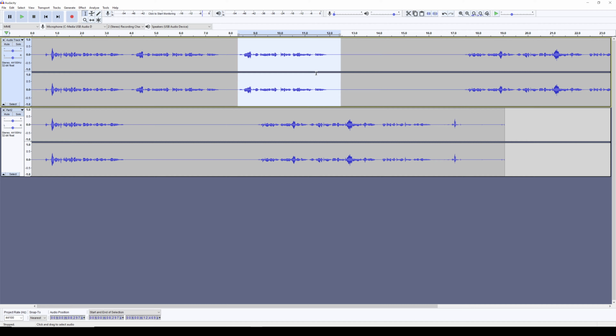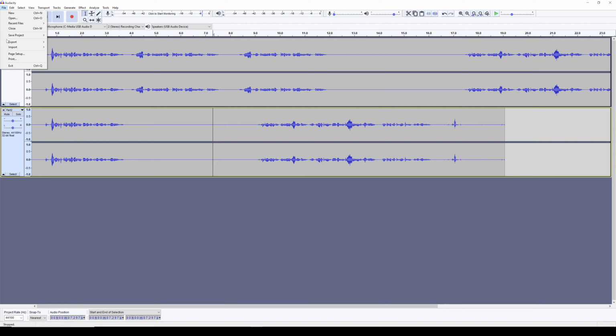So the other thing I want to talk about in this video is exporting. So we imported audio, we also want to export audio. So now that I've got everything set up the way I want, I'm going to go to File, Export, and then I choose the file format I want to export. I mentioned before that Audacity supports MP3, WAV, and OGG.